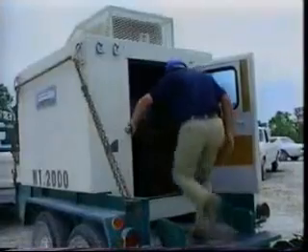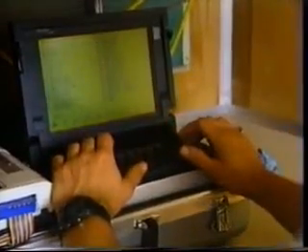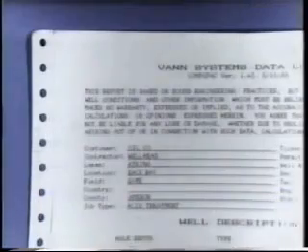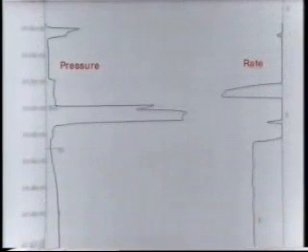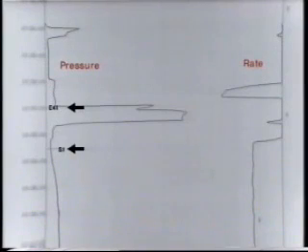This treatment has the advantage of a computer monitoring system. It records basic well data, downhole equipment and conditions, and treating fluid volumes and properties. Treatment pressures and injection rates are recorded on a time-coded scale. Notations can be included on the chart to indicate significant events such as pre-treatment test details, slurry stage, anomalous pressure behavior, and perf ball response.